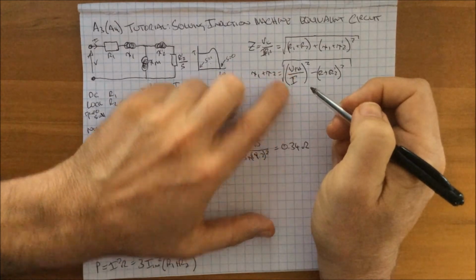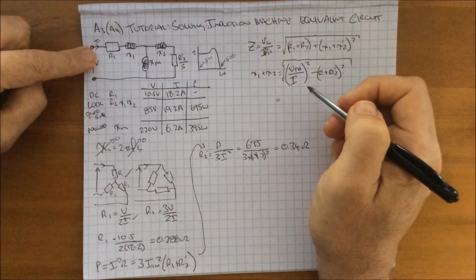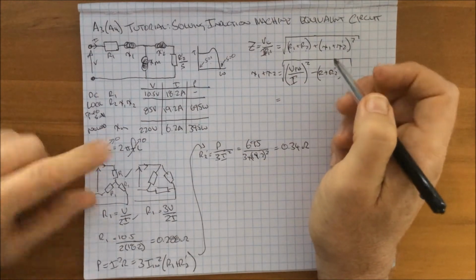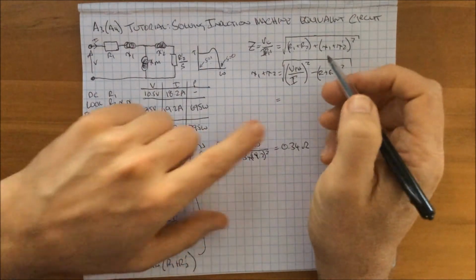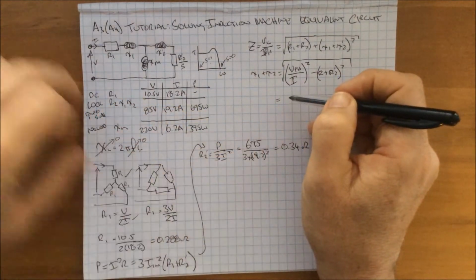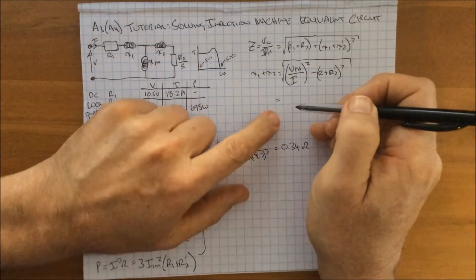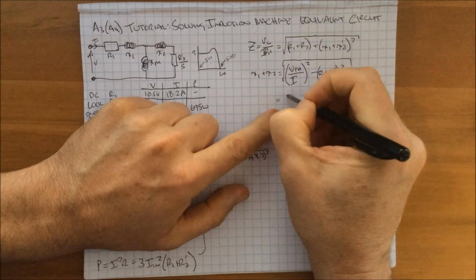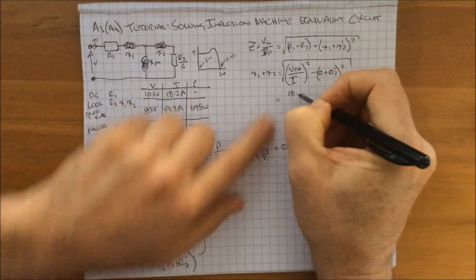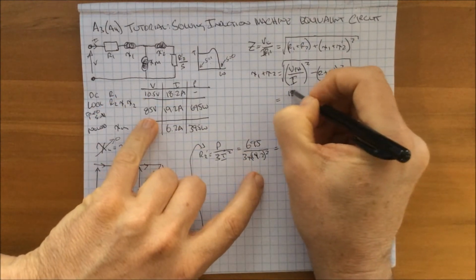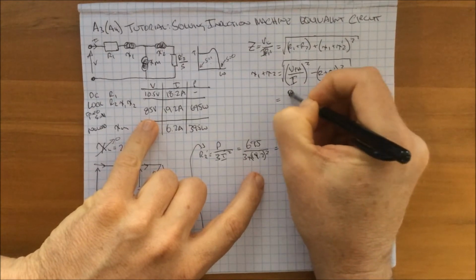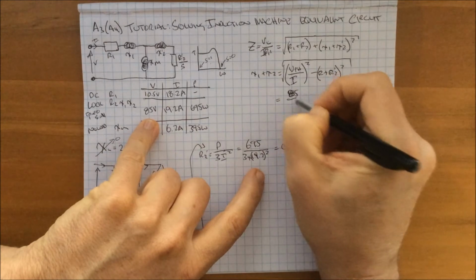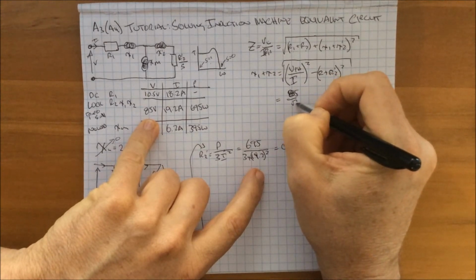This is the phase voltage that we're looking at here, because it's a single phase model. We've got a line voltage, so we need to adjust for that. Important note, this is where a lot of students go wrong, put the wrong values in. So we end up with 85 volts that we measured, which we need to divide by root 3 to convert it to our phase voltage.